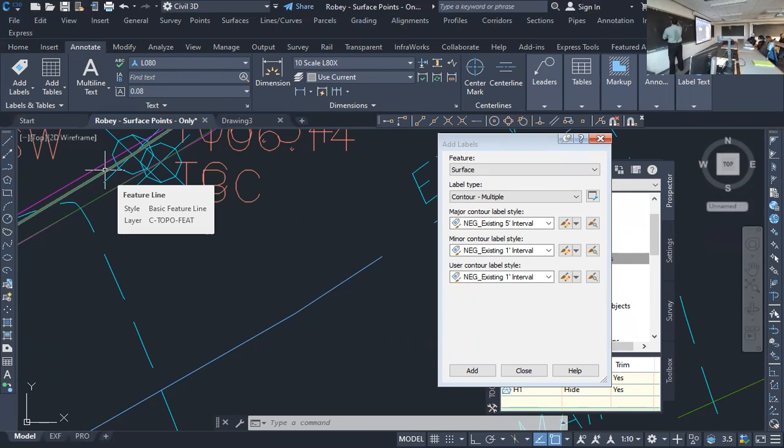And this is your concrete sidewalk. So if this is half the road, and this is the center of the road, the feature lines that I would draw along the longitudinal length of it would be the center line, bottom of curb, street side, top of curb, away from it.